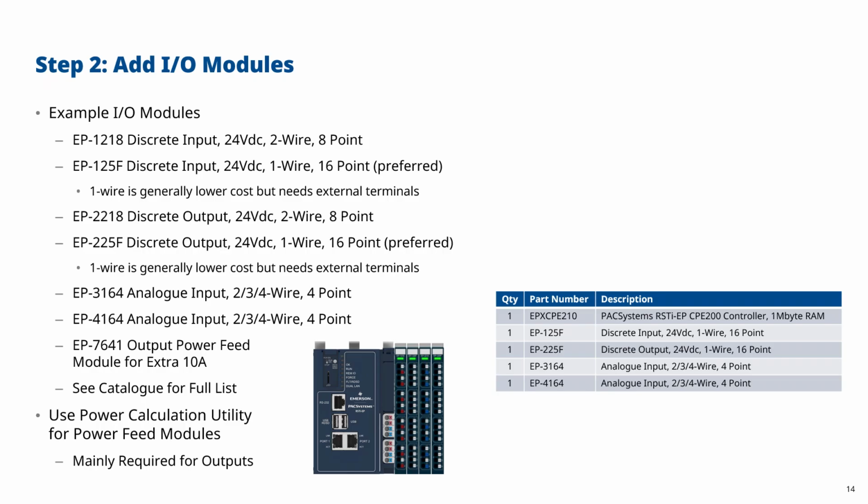So for example, if you were requested for 128 inputs, you divide 128 by 16, so that means you would need 8 of the 16-point modules, because 8 times 16 is 128. There might need to be a calculation there for spares. Often I see specifications ask for an I/O count and then specify 20% spare on top.